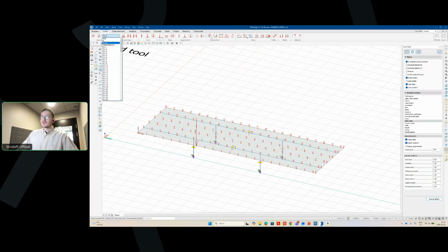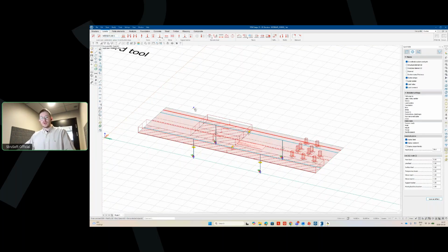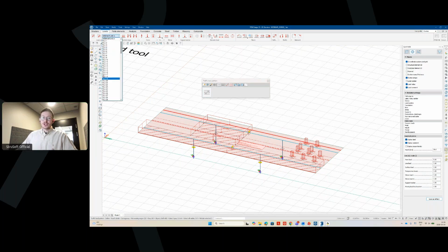and let's go back to the load pattern we created. I want to also show you, so now we created one load. What if we want to create one load more? Then the mistake that a lot of users do is that they use the define tool once again. And the problem here is that every time you use the define tool, you will get these unit load cases. And if we're interested in the same surface, that is completely unnecessary. And we don't have to do that.